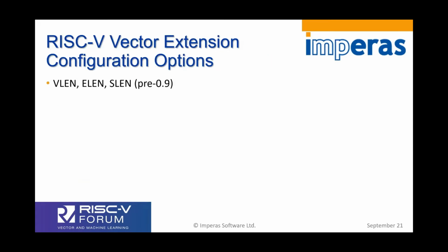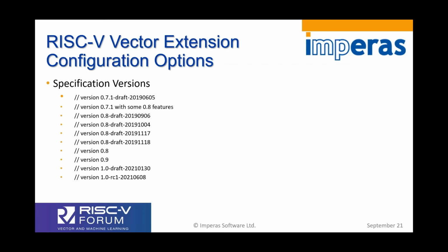I hope that has given a brief introductory glimpse into the complexity and requirements of a reference model for RISC-V design verification. Let's now start to look in a bit more detail at the specifics of the vector extensions. So once again, let's look at the alternates within the vector specifications. Firstly, we have the configurations containing settings for VLEN, ELEN, and SLEN. SLEN configurations were actually only relevant in specifications pre-0.9. Which once again leads me nicely into the fact that the vector specification has also been going through a number of iterations. And as mentioned previously, we have designs which are being targeted at different specification milestones which we have to handle as part of the reference model.